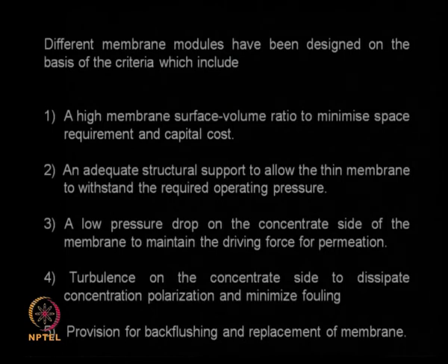We will have to have good structural support, because if the membranes are very thin, we need a good backing structural support if you are operating at very high pressure, otherwise the thin membranes will just break. We want to maintain a very low pressure drop on the downstream, that is on the concentrate side of the membrane, so as to maintain the driving force for the permeation.